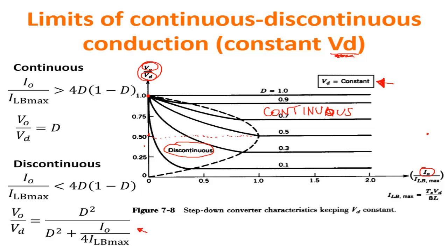This finite state machine essentially has to know whether the output voltage is increasing or decreasing with respect to the value that you want, and depending on it, it has to adjust the duty cycle. In the most complex DC-DC regulators, this is done by a microcontroller. In the simplest situation, it is done by a simpler finite state machine, but you need to have some.